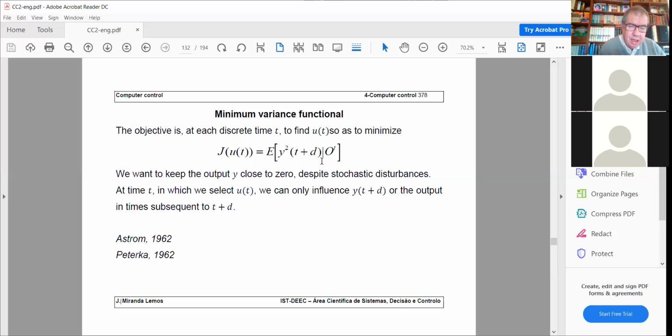That is to say, if you have a zero with a radius, say 5, and some angle theta, the pole will be at position 1/5, that is 0.2, and angle minus theta, mirroring in this sense.